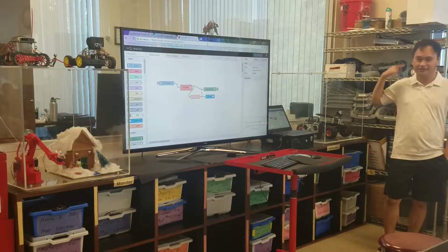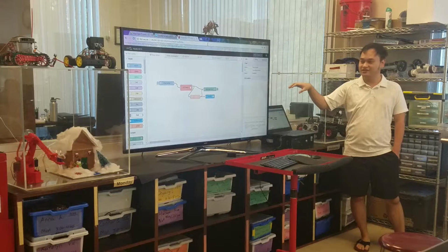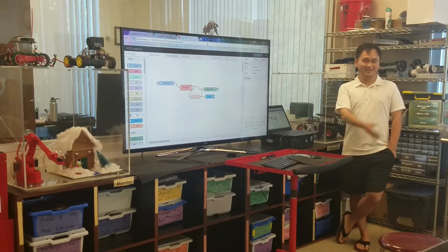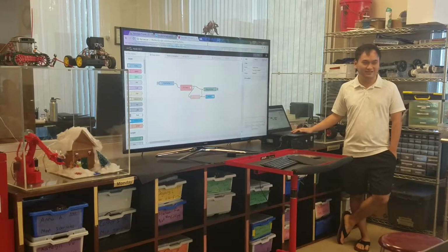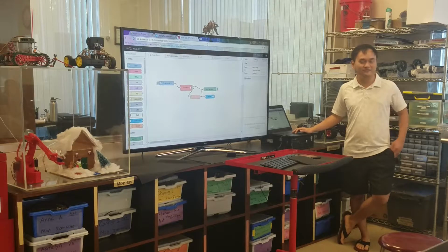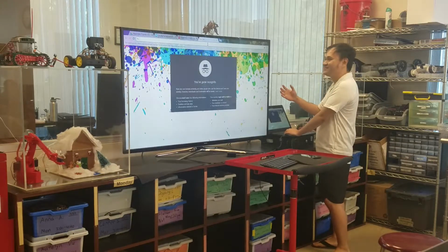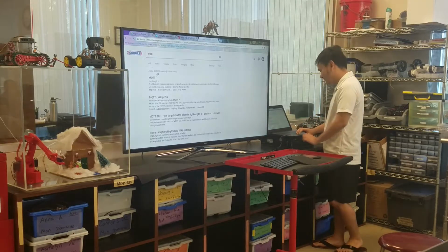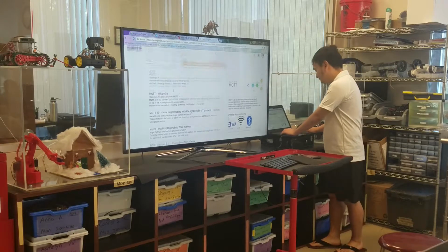If you want to upload it to a server, to the cloud, and control your Raspberry Pi without using this, you have to have more knowledge about port forwarding on your routers. Port forwarding, and maybe another way is to use MQTT. Basically, it's a public broker, publish and subscribe. For MQTT, the most popular one is Mosquitto.